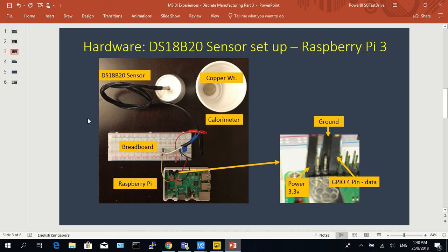We take off the SenseHat module and connect a DS18B20 temperature probe to the Raspberry Pi. The probe has power, ground, and a data line. Note, we do need a 4.7K resistor. We make the connections using a breadboard. Note the wiring connections on the GPIO. We connect the data cable to pin 4.